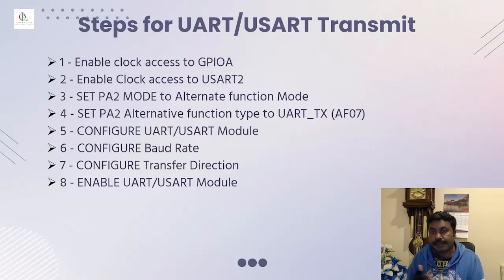As you learned from previous sessions, every port's pins can be used as an input, it can be used for output, it can be used for alternate function mode, or it can also be used for analog mode. So there are basically 4 port modes that you can use, and set and configure.